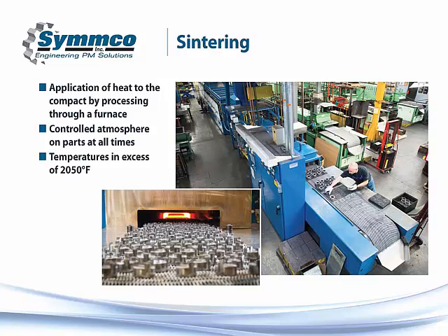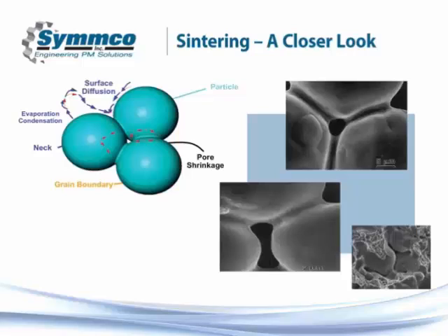But I want to take a minute and take a closer look at sintering. Compaction, running those presses, is a very mechanical process. The compaction operators are very mechanically minded. Sintering, however, is a very physics-type process. Again, as we said, it goes into that furnace up to about 2,050 degrees Fahrenheit. And one of the keys there is understanding that that temperature is always lower than the melting point of the main constituent. Let me say that one more time real quick.